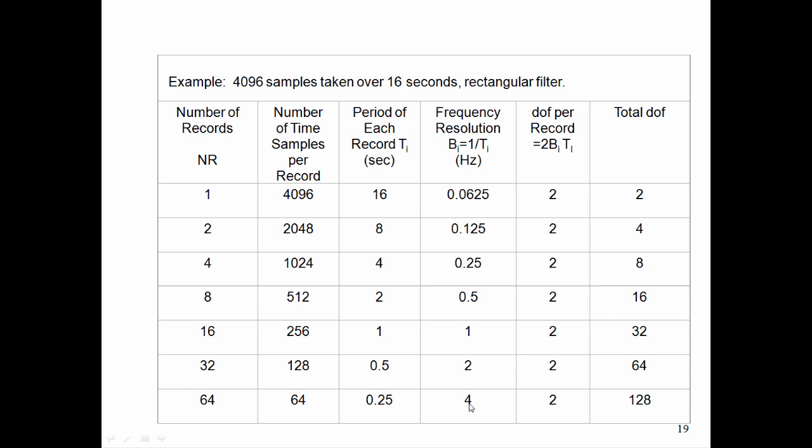And the reason we would want to do this is because we want to smooth out the data so we can demonstrate compliance within tolerance bands. Because on the other hand, if we had 1/16 of a hertz, we might show that certain spectral lines exceeded the upper tolerance bands, or certain spectral lines dropped out below the lower tolerance bands.